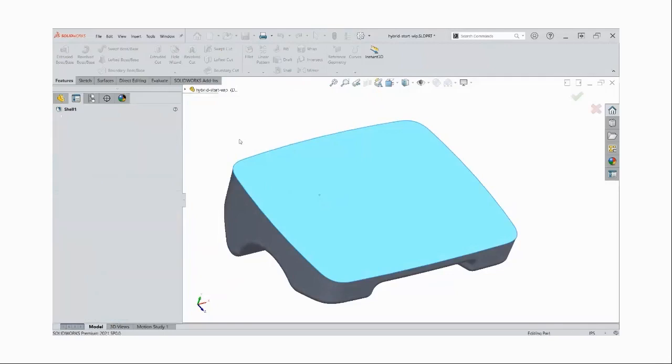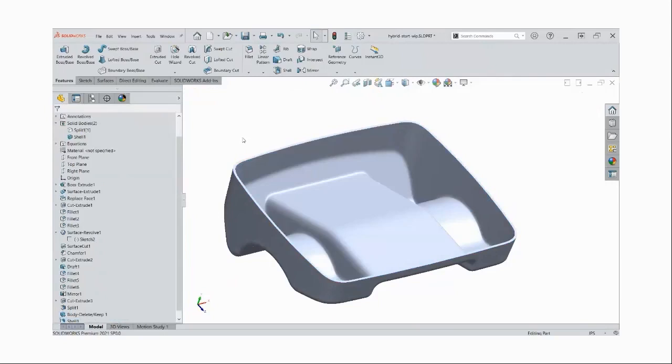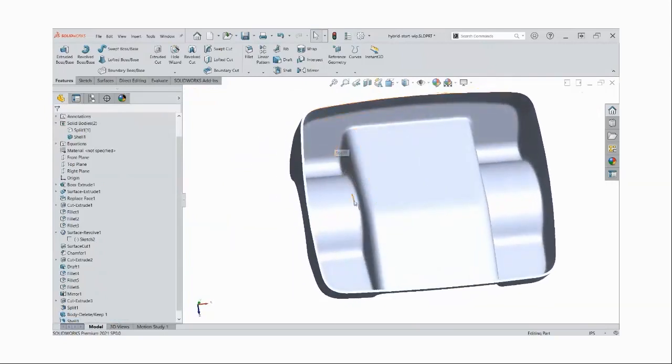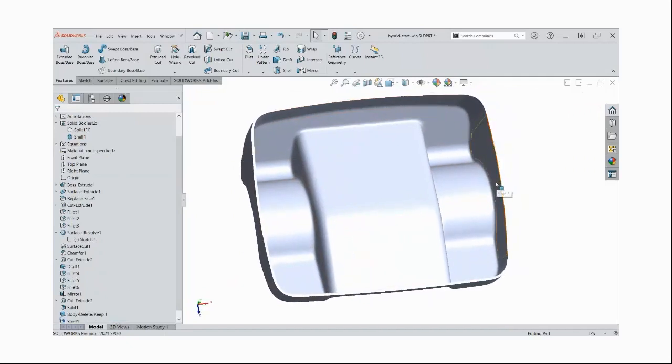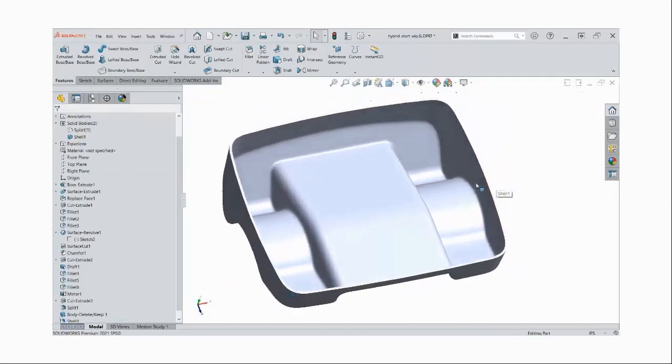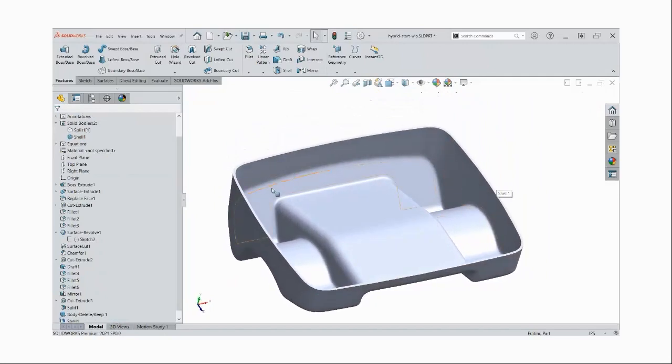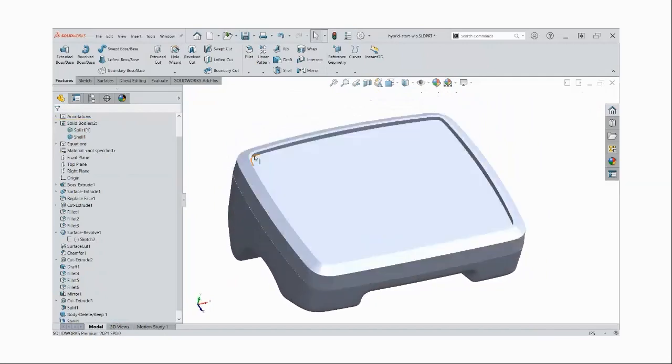And shelling is where you're liable to run into problems. So if you had fillets and really just dirty geometry that wasn't as clean as it could be, then you might not be able to shell correctly. But in my case, that one worked fine. Let's try our luck on the other side.